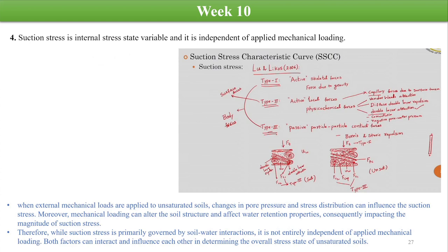Moving on to the fourth question, which says that the suction stress is an internal stress state variable and is independent of applied mechanical loading. We can see that when external mechanical loads are applied to unsaturated soils, changes in the pore pressure and the stress distribution can influence the suction stress.